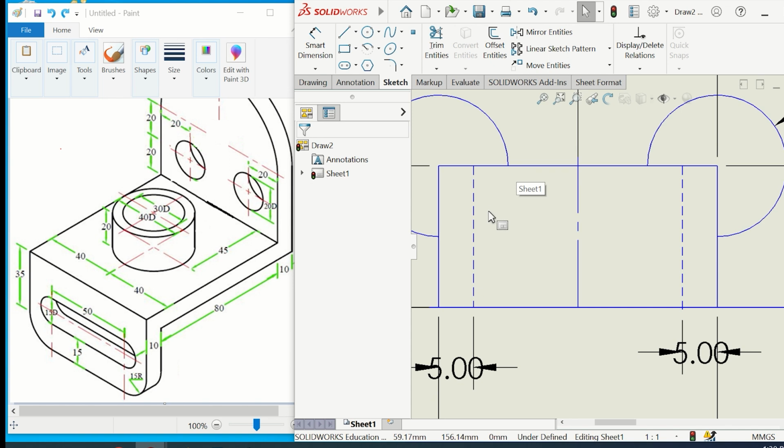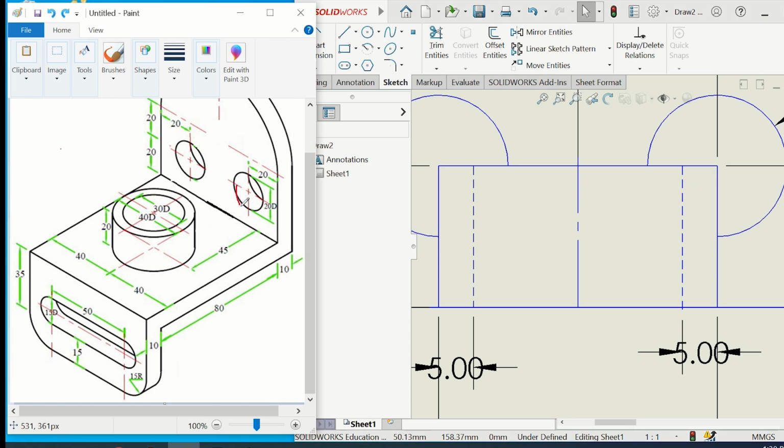However, in engineering drawing, as I was saying, we always represent hidden edges that exist here, in this edge. It surely exists, but I cannot see it. There's something that's standing between my eyes and that thing here, which is the cylinder. So here, you need to simply draw an arc, and you need to make it a dashed arc.